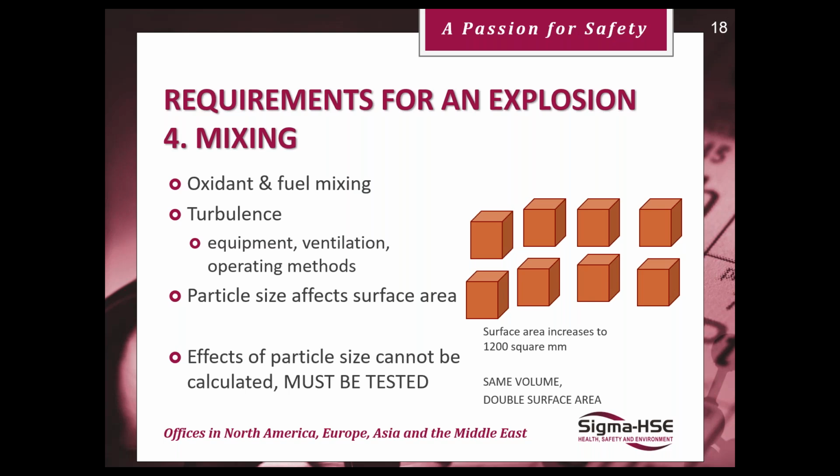So given those attributes, that just illustrates what I mean by the surface area increasing per volume. Any heat that's generated by the oxygen reacting there cannot be lost, cannot be conducted away into the bulk of the powder. So the heat will be generated almost adiabatically, and hence the exothermic reaction will go to completion very rapidly. The larger the granule, the less reaction occurs, less heat is generated, but also the heat that's generated will be conducted within the body of the particle, and that will stop it from bursting into flame or exploding.